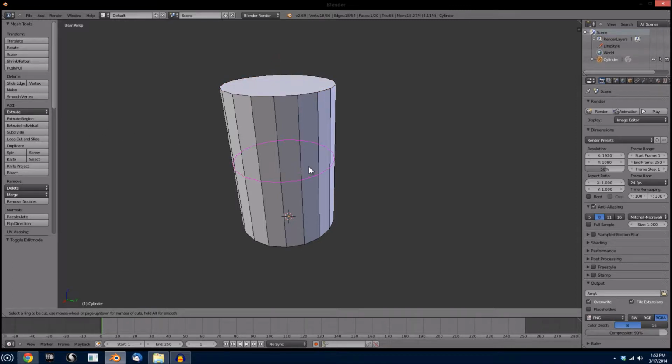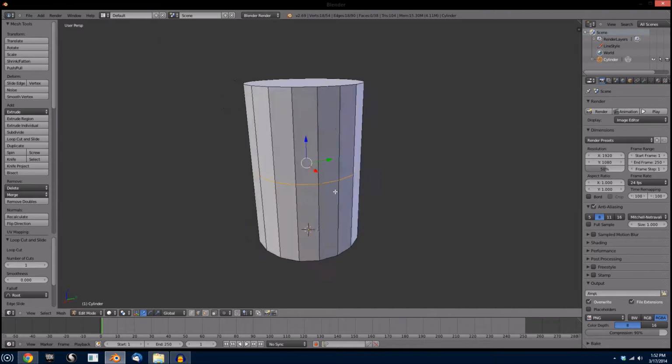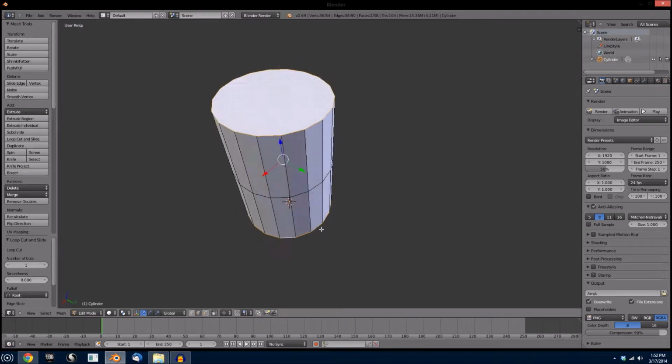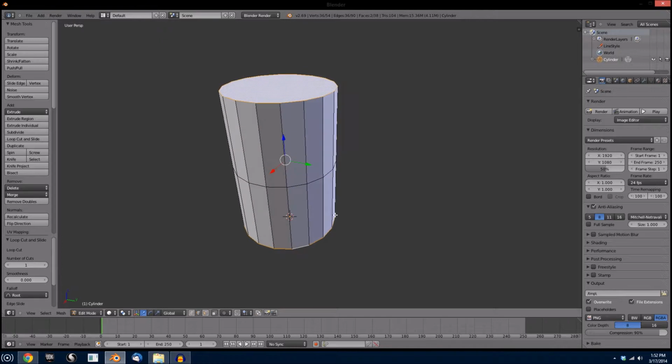Again, just click the left mouse button, which goes into slide mode, and we click outside of it with the right mouse button. Okay. And we're going to go into edge select mode again. Hold Alt, select the top face. Hold Shift Alt to select the bottom face as well. Anytime you hold Shift, it's giving Blender the command select this too. So now that we've got both top and bottom faces selected, we actually can hit scale.